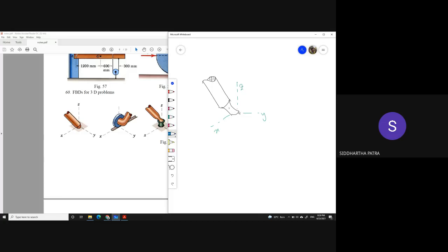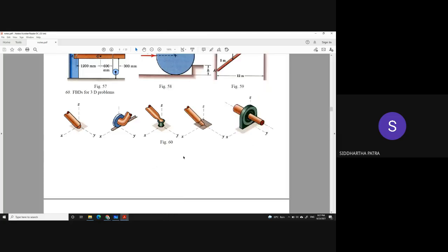Therefore, it will be receiving reaction forces in all the 3 directions, because through these reaction forces that support, that fixed joint, is trying to prevent any kind of motion of the rigid body. So these reaction forces are there to prevent the motion. And then you have Mx, My, and Mz. So that is the 4th one, and then the last one.